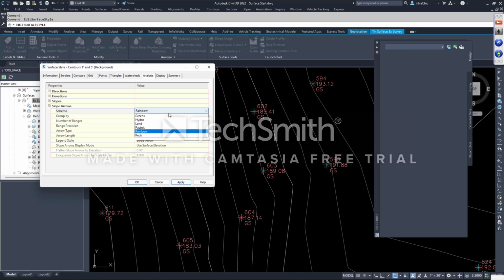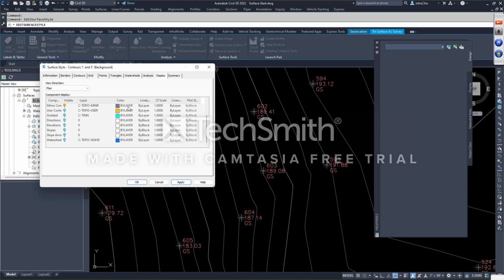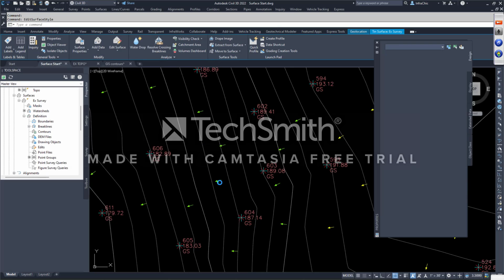What type of scheme are we going to start with? Do you want rainbows, reds, blues? How do you want it to look? So when we set it up in the surface object, it came out with this color scheme, red, green, blue, and that's because it was on rainbow. But what if I had told it to do land in the style and then go to the display tab and turn on slope arrows and hit apply? And I hit OK. Hold on.